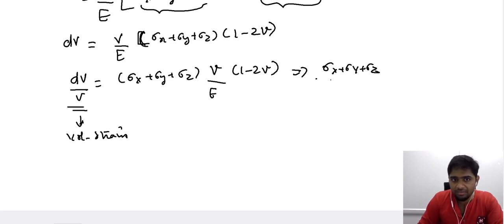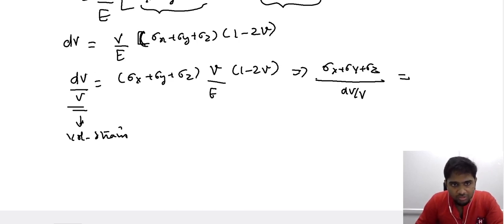So we have in the numerator the combination of all the different stresses that we impose when applying a triaxial tensile loading, and when we bring this term here, we have dV by V. So we have the sum of stresses that contribute to the mechanical condition, and the resulting volumetric strain. We brought this overall term downwards, and when you do that, we also end up having E by 1 over 2 minus nu.